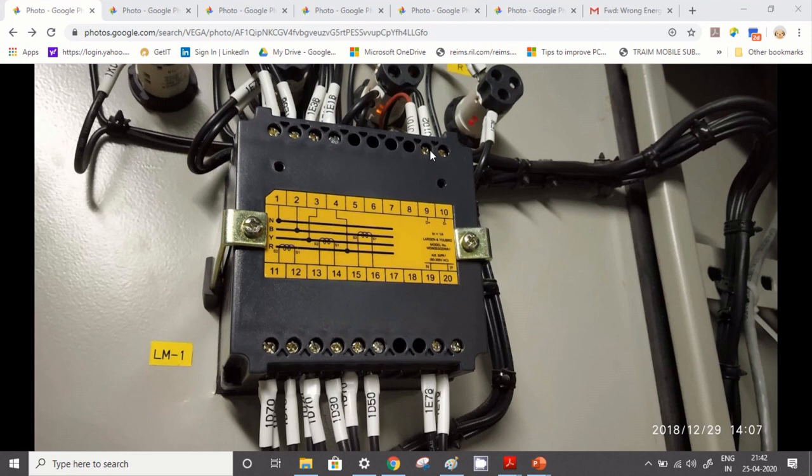So this is a limitation, because once the scale reaches the gigawatt hour, your reading will only appear at some random interval, like 15 days or maybe 30 days, whenever your energy is consumed. So that is also one reason in which you cannot do anything, because we do not know how to reset the kWh counter of this meter. So there we need to replace the meter with the appropriate make as per the engineering guideline.